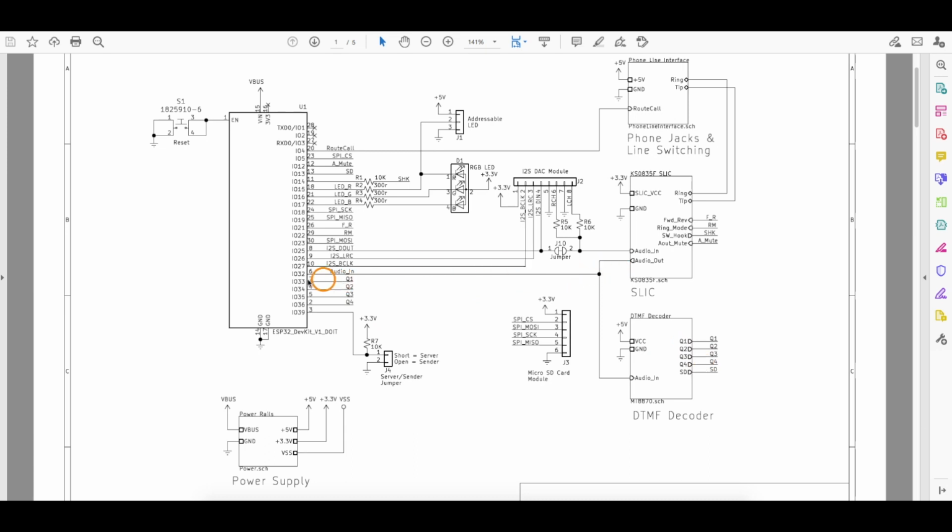And also if we want to use the ADC on the ESP for some purpose to do something else with the audio, we have that capability here. Generating audio out of the ESP to go into the phone line is useful because that's how we can generate things like a dial tone when somebody picks up the phone. That tells them the phone is active. And the other call progress tones, like if they just dialed a number and the other end is busy or ringing, those tones are played from the ESP into the phone line this way.